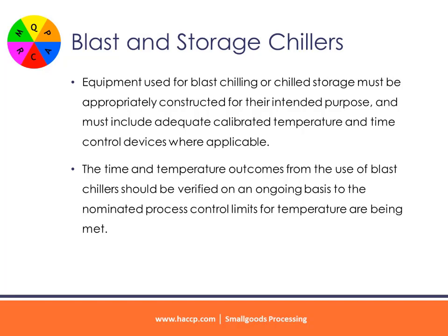Blast and storage chillers. Equipment used for blast chilling or chilled storage must be appropriately constructed for their intended purpose, and must include adequate calibrated temperature and time control devices where applicable. The time and temperature outcomes from the use of blast chillers should be verified on an ongoing basis to ensure the nominated process control limits for temperature are being met.